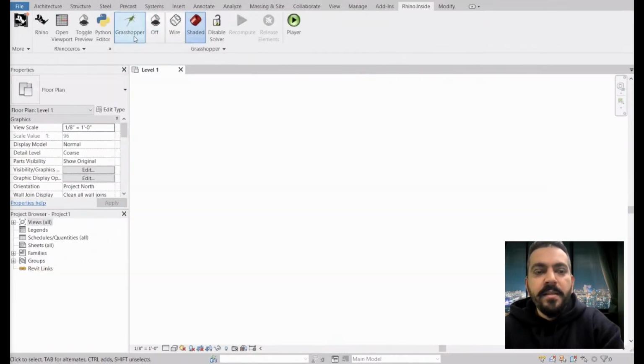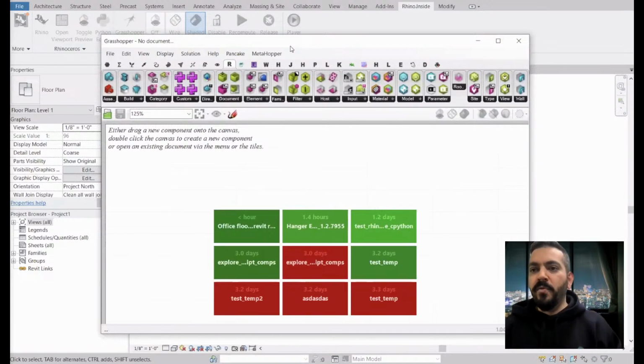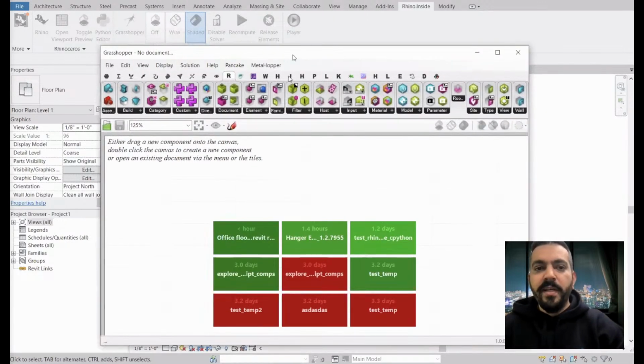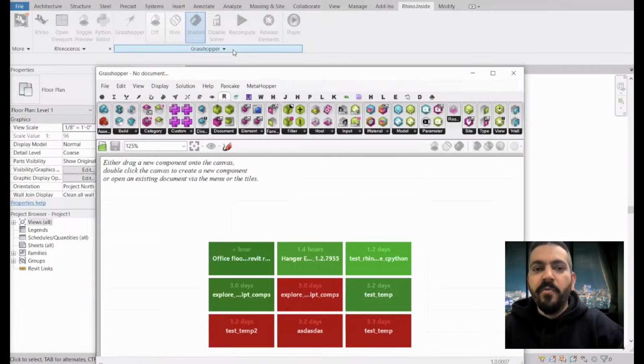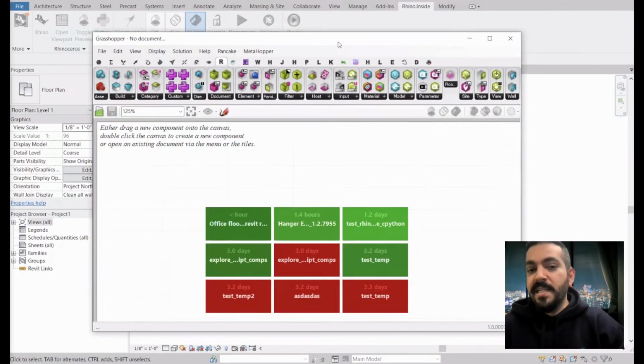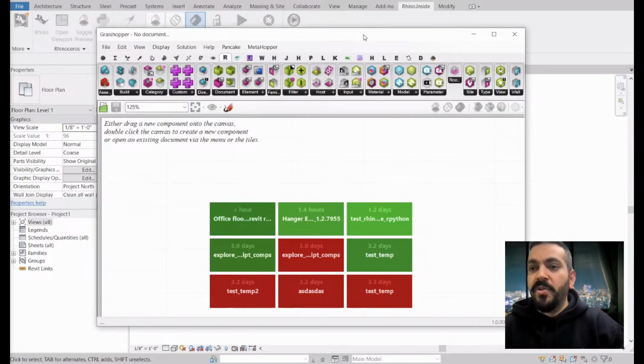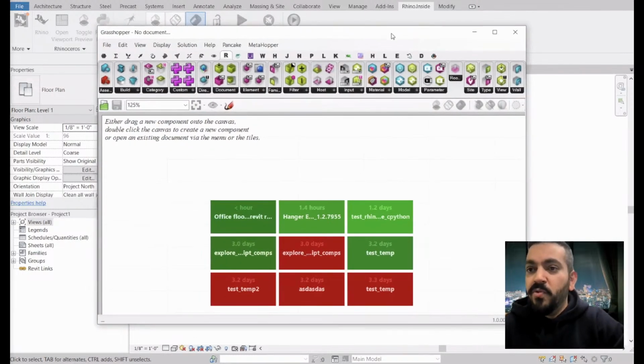And then the second thing is Grasshopper. Grasshopper is the visual programming plugin for Rhino that we talked about. We have created a dedicated tab for it, so you can control its features and all that kind of stuff. Because when I personally talk about Rhino inside Revit, one of the most important aspects of it is access to Grasshopper, right? Everything else that's in the backend that Grasshopper uses is also important, like the geometry engine to do geometry booleans and conversions and all that kind of stuff. But this is one of the main ways that we actually use Rhino inside Revit.